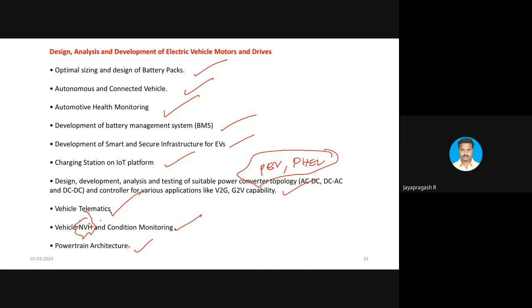It should provide a path for the demagnetization of the winding, and the demagnetized power should be utilized in a productive way by feeding power back to the source. So by considering all these factors, we have to choose the appropriate power converter. According to the survey, the asymmetrical half-bridge converter is the best power converter to operate the SRM in a satisfactory manner.